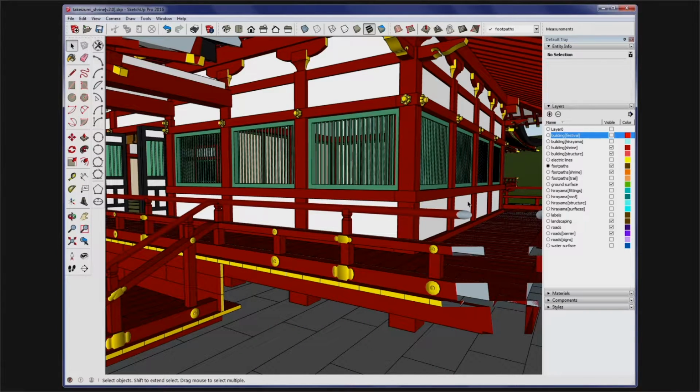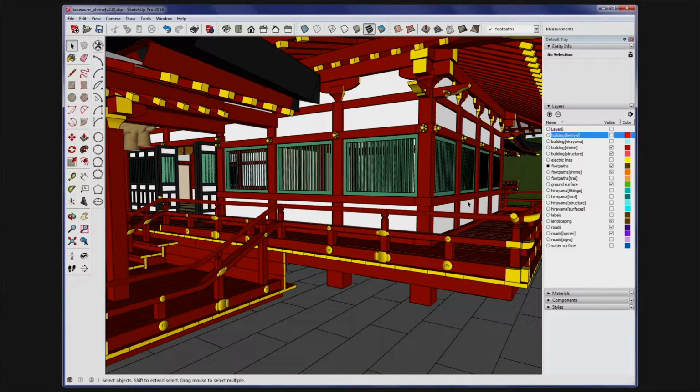They're all there. And if I wanted to change one of them, depending on the software that you're using, each one of these is a component. So if I wanted to change one window from one type to another, I make that change once, and then it changes every single window of that type in the model. So it's really good at maintaining consistency in your workflow there.